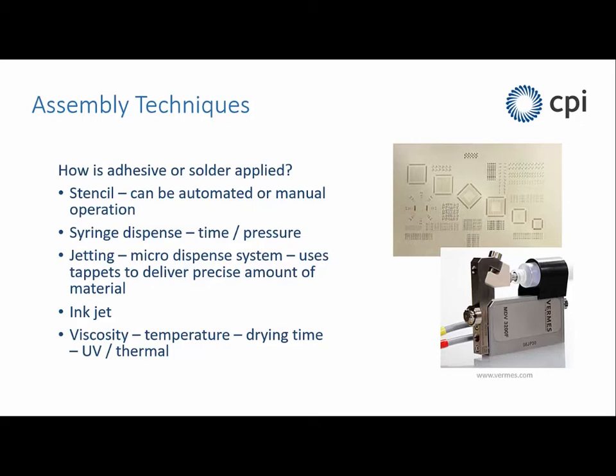And inkjet is also quite possible for dispensing adhesives, although that tends to be challenging because the adhesives often have a rheology that doesn't really match well with inkjet dispensing. And you've got to consider things like the viscosity, the temperature, the drying time. Many of these adhesives are thermally dried rather than UV. UV works okay, but if you've got a lot of silver in your adhesive or your ink, then the UV tends to get scattered or reflected back, and so you don't get very good curing. So thermal curing is most common for these materials.